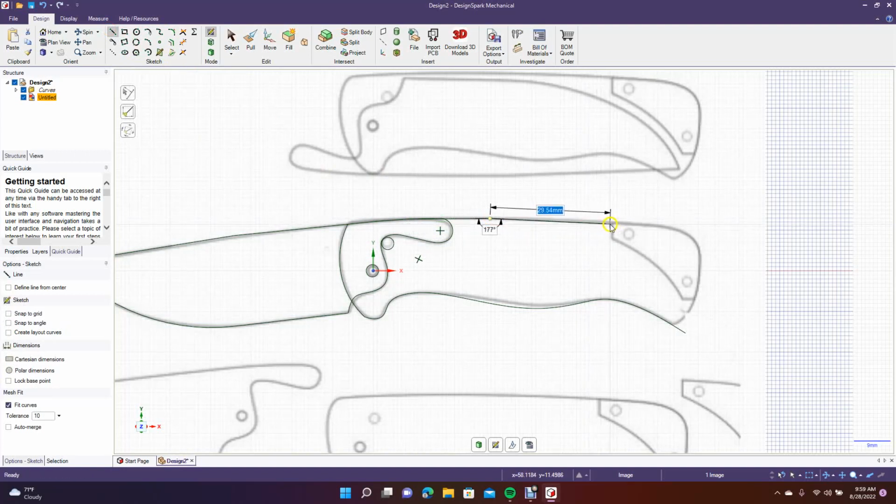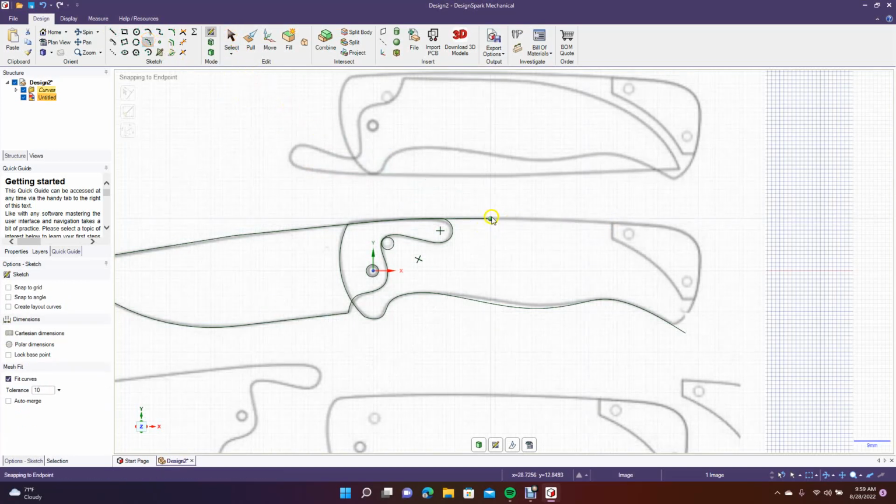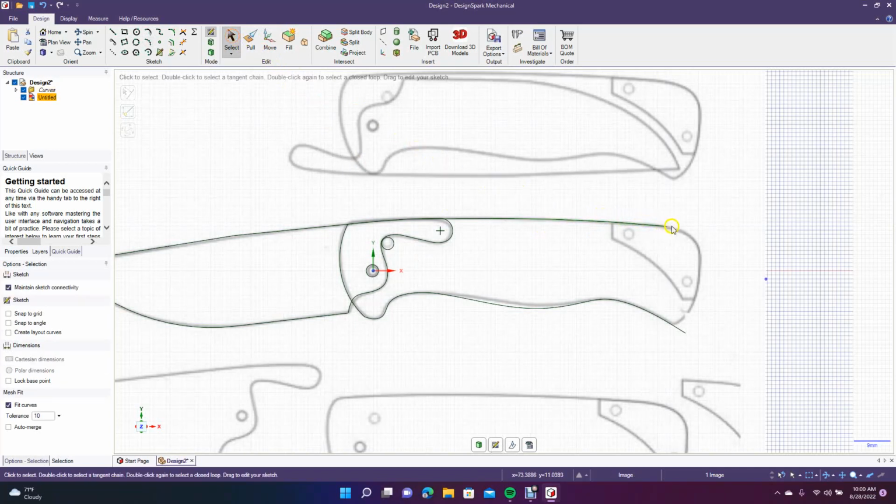We want to draw a couple of these. Actually, I'm going to draw one, select the click off, then get the 3-point arc. Then we're going to go from here over to here. It's a little bit of a curve in there, not much. And then we'll click there. Now I'm going to use the spline tool to draw this part of it here. So we'll get our endpoint, click, curve, click, curve.